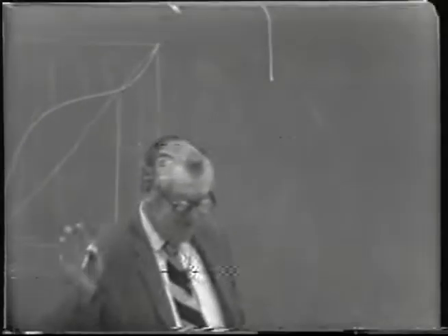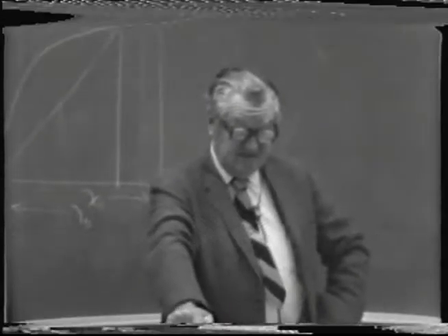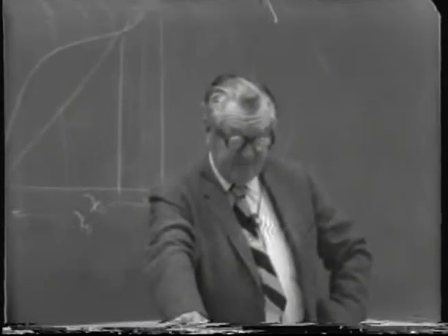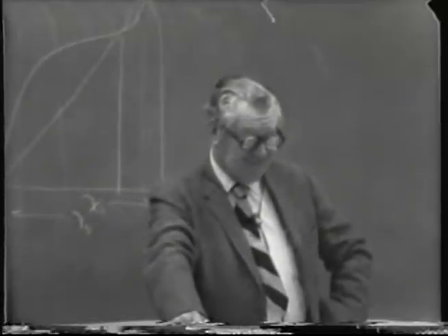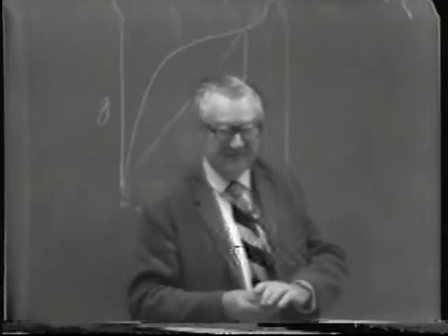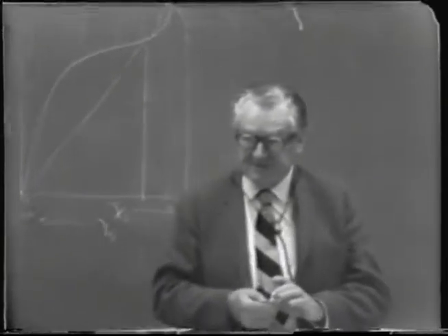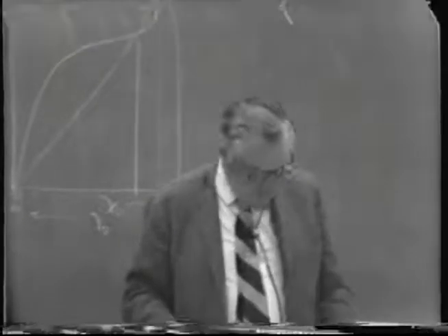So this is going back to some things we've had earlier. In other words, you can separate a mixture into its azeotrope and one of the pure components, but the pure component you'll get will be the one that's on whichever side of the azeotrope you happen to be in the composition of the feed that's being distilled. This okay? All right.